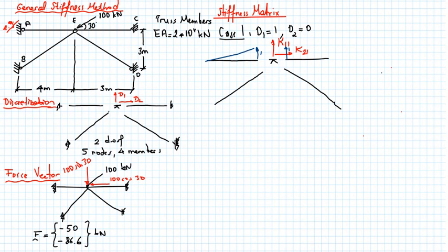So with these given loads, I have a unit translation here that's equal to 1, no bending. So this is the deformed shape of the first truss member, deformed shape of the second truss member. So this is also 1, that's also 1. So that's the deformed shape. Now, what we need to do is for this given deformed shape, we have to calculate the forces.